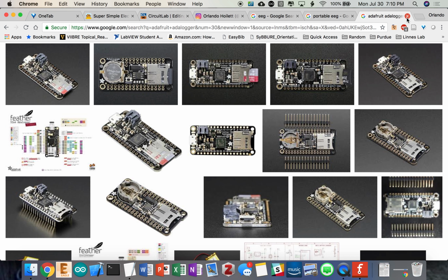If you ever get into power electronics, they're used a lot there because they essentially are short circuits at DC, which is what the power supply voltage will be, and high impedance at high frequencies, the opposite of capacitors. That's more conducive to working with power circuits than with just making general purpose filters. Okay.